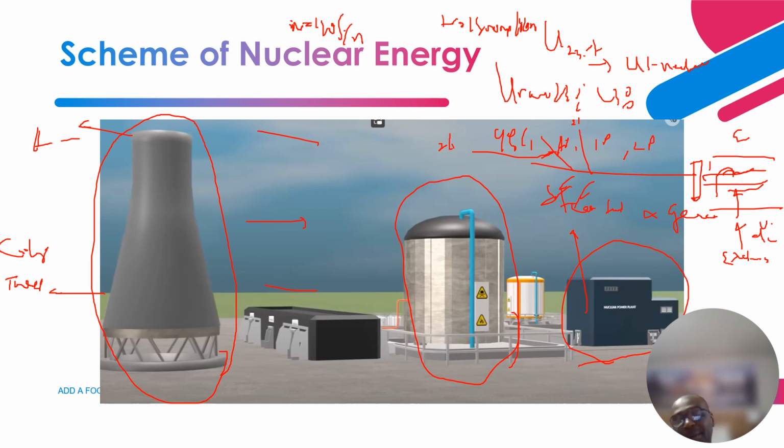If you have a small number of poles, like a cylindrical rotor, which has 2, then 120 times 60 over 2, that is about 1800 RPM, right? On the other hand, if you have about 100 poles, that translates to only 18 RPM.